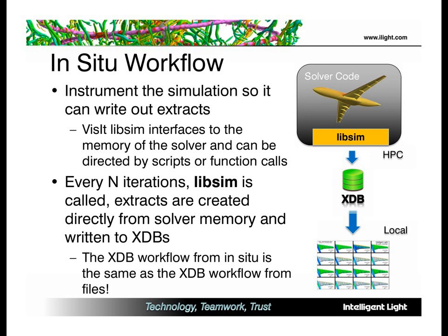Once you have the XDB file, the XDB workflow is exactly the same as it was from working with files. So you can get started working with files and migrate towards an in situ situation later. The contents of the XDBs are exactly the same, whether they come from VisIt or they come from FieldView. And in fact, I should mention that XDBs are fully solver independent. That is, once you have an extract from Overflow or a commercial code like STAR-CCM+ and you're doing subtractions or things like that, FieldView does not care. It's just essentially an extract with variables on it.